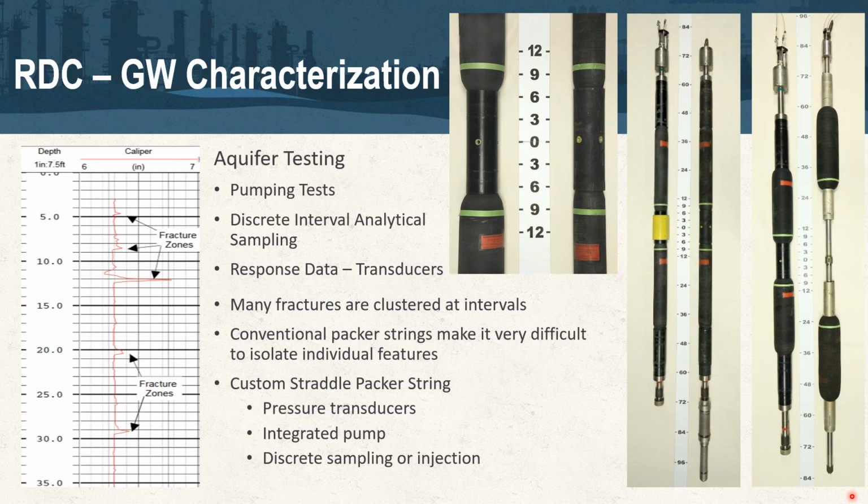And looking at the bullets here, this straddle packer has a Grundfos ready flow tube pump in the bell chamber at the bottom. It also has transducers located within the packer element itself, one above the packer for looking at hydraulic characteristics above the packer element, one within the element, and then one below the element looking at vertical connectivity or vertical seal within the borehole itself. And this, coupled with transducers in the surrounding formation itself, allows us to look at hydraulic characteristics during pumping tests, not only within the borehole itself, but within the surrounding formation closest to the point of pumping from that well.